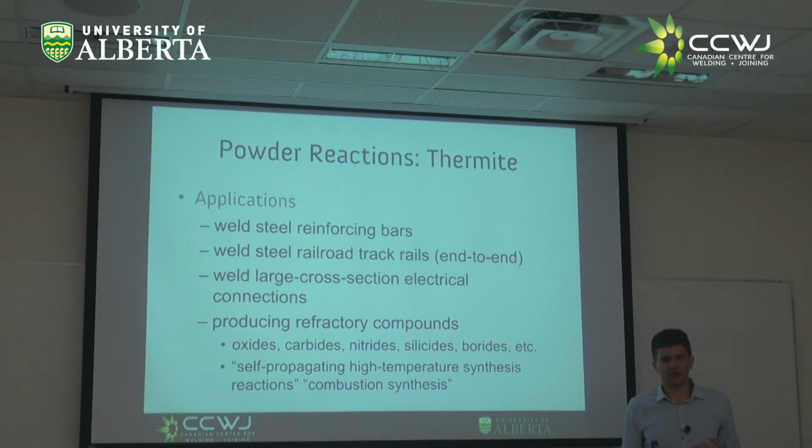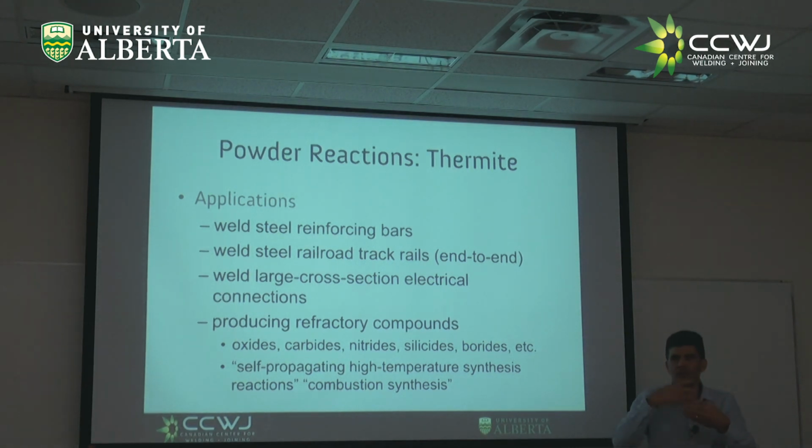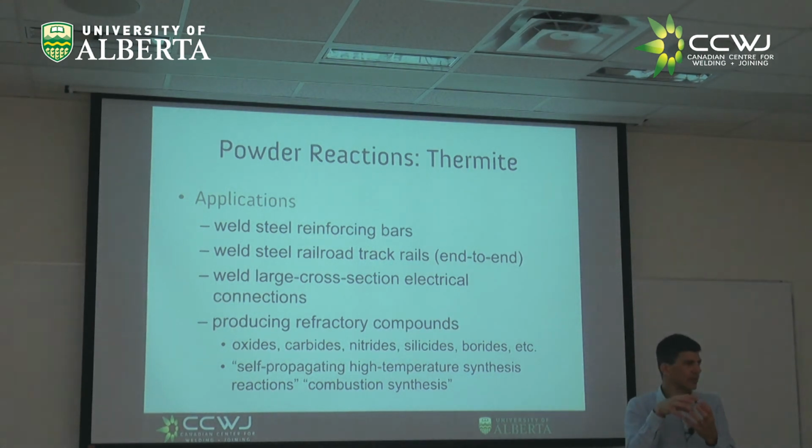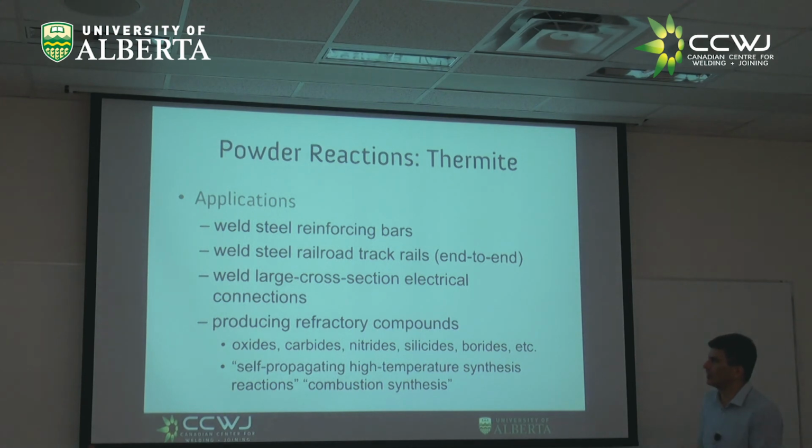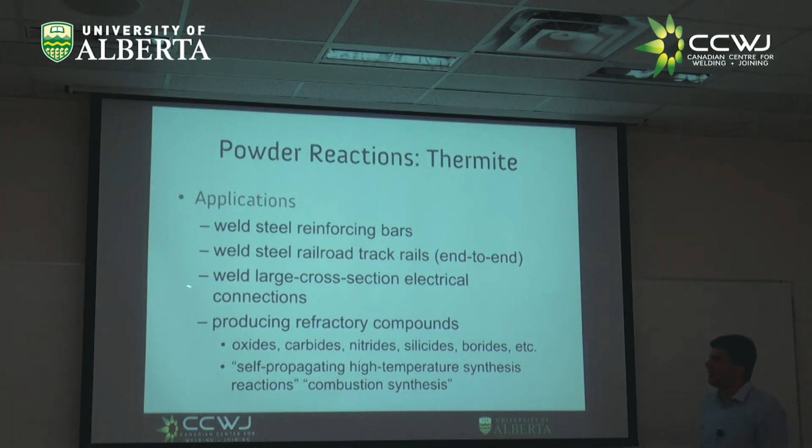So thermite is somewhat similar. Do you remember when we talked about electrogas or electroslag, in which we have essentially a swimming pool of metal, right? And we have it combined. In the case of electrogas or electroslag, it was the plate on two sides and then copper shoes on the outside. In this case, you have your rebar or your railroad tracks surrounded by all this refractory environment that will contain the molten iron that is very, very hot, right?